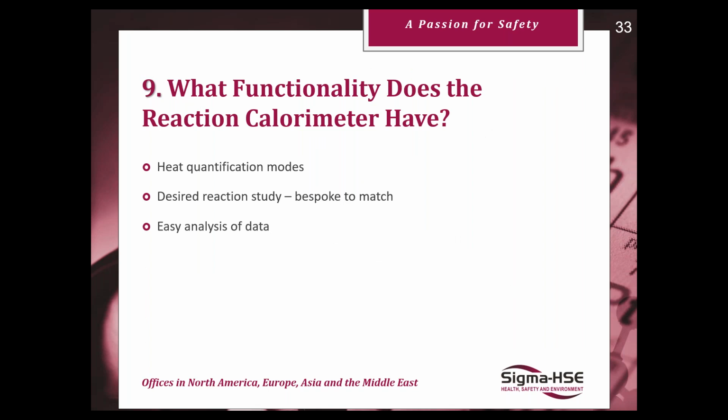Okay, so we've talked about it quite a lot already, but we'll look at reaction calorimetry now. So question 9, what functionality does the reaction calorimeter have? Yeah, so the reaction calorimeter is especially useful for modeling large-scale batch reactions. It has automated dosing capabilities, and it's very representative of the flow dynamics you'll see with large stirrers in these pilot scale and above processes.